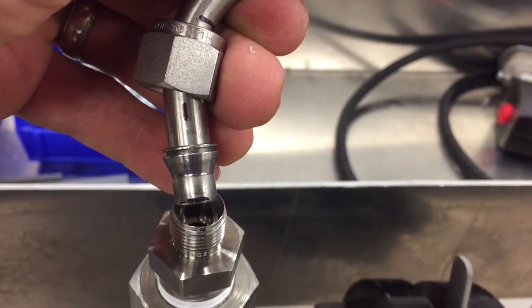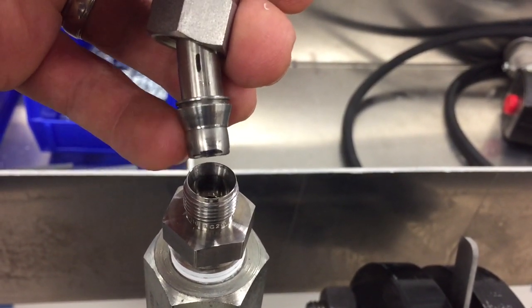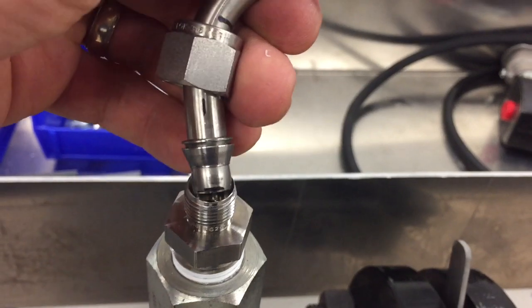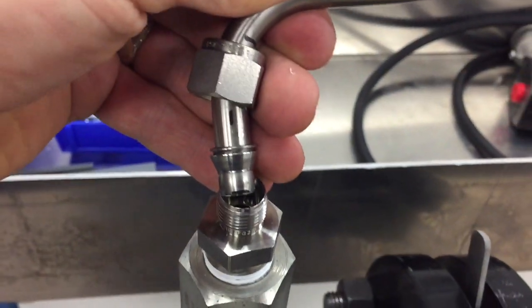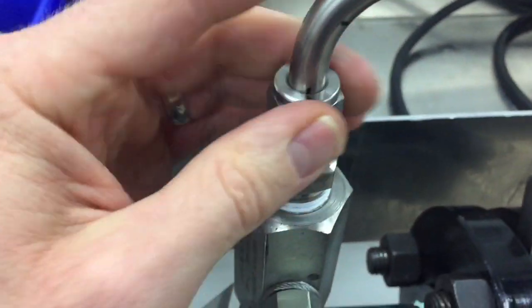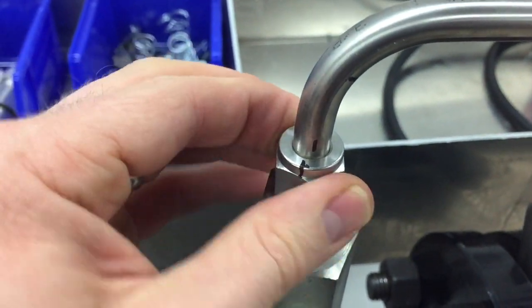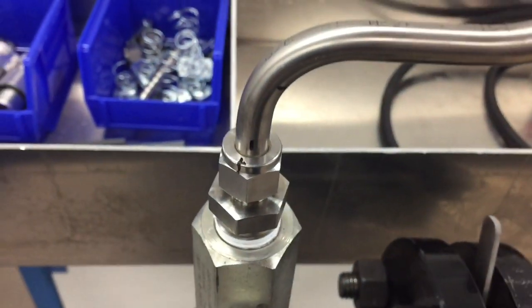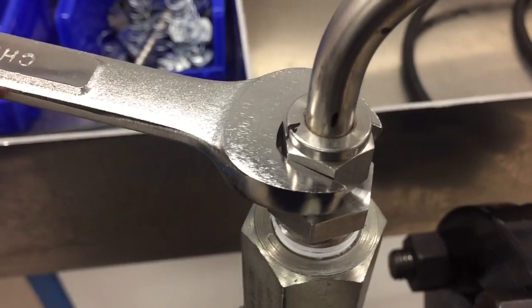So it's very important. If we didn't have enough straight run of this tubing, there might not be enough for it to bite down on, and we want to make sure that the tubing is seated right down on the bottom of the fitting. So this has been done correctly. We can install it, and basically now we just need to tighten the nut back down. You can see I can get just past one turn now. If I just use the wrench here, I can snug it right back up and give it that extra 1/4 turn that's needed, and now it's installed back properly.